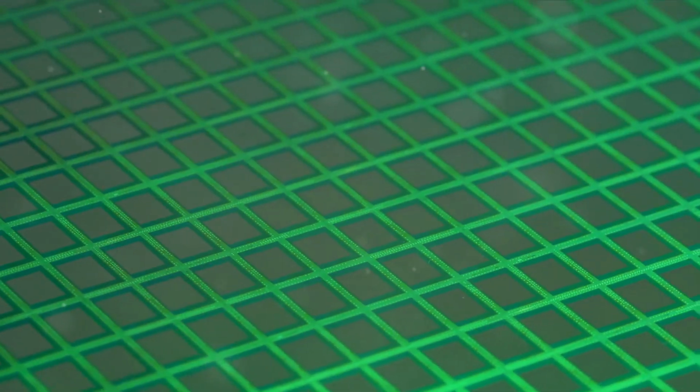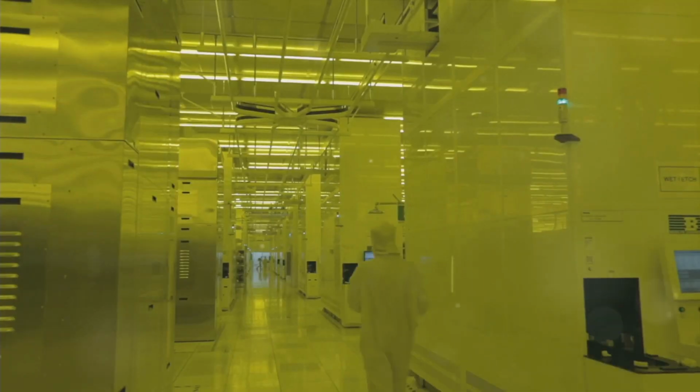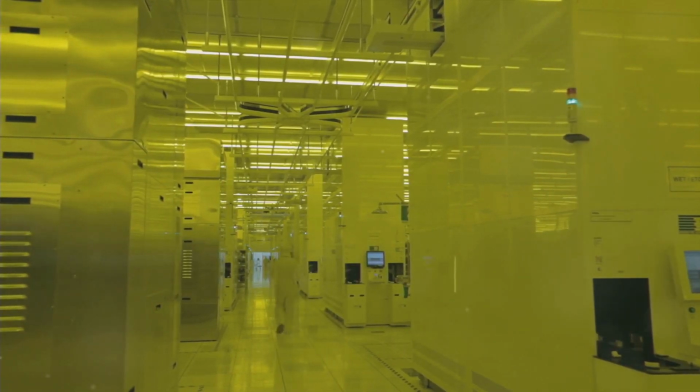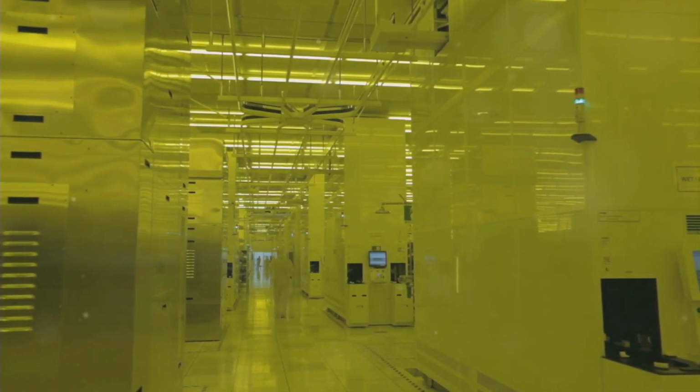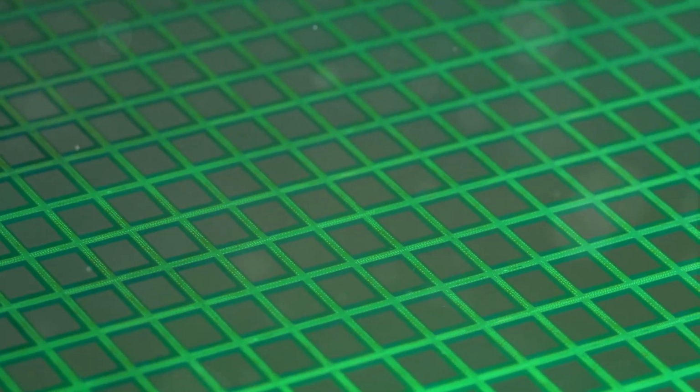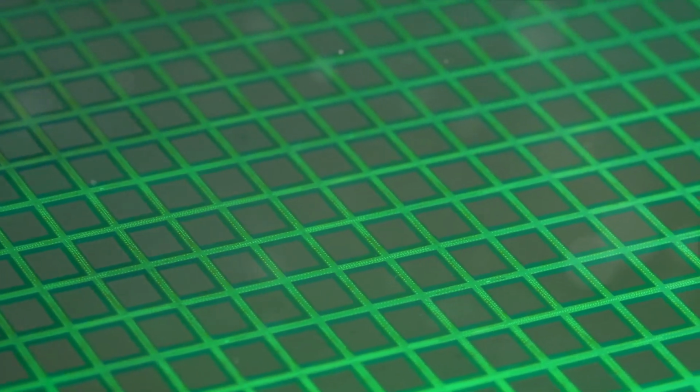Semiconductors can be classified into two types based on the impurities added to them, P-type and N-type. The P-type, or positive type, is doped with elements that have one less electron in their outermost shell than the semiconductor, creating holes or positive charge carriers. On the other hand, the N-type, or negative type, is doped with elements that have one extra electron, creating negative charge carriers. Now imagine bringing these two types of semiconductors together.